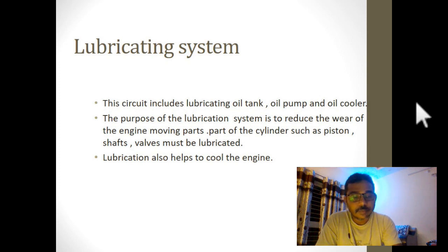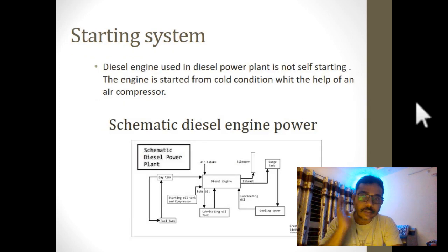Starting system. The diesel engine used in a diesel power plant is not self-starting. The engine is started from cold condition with the help of an air compressor. You can see the line diagram where the air compressor is used, where whatever air is supplied to the diesel engine is compressed to high pressure and high temperature. And definitely, when we are using high temperature and high pressure air inside a diesel engine, the combustion will be easy.